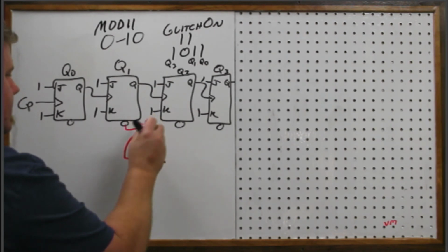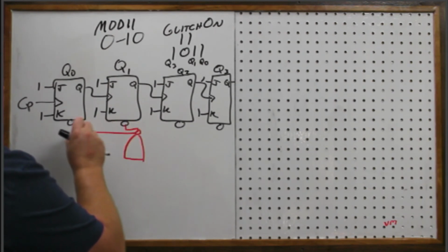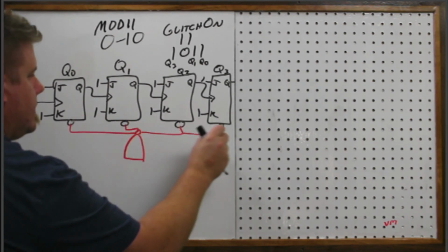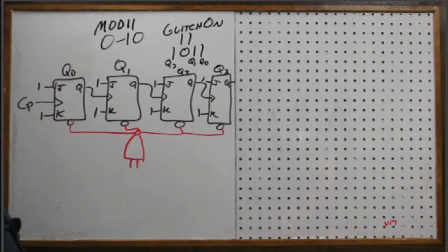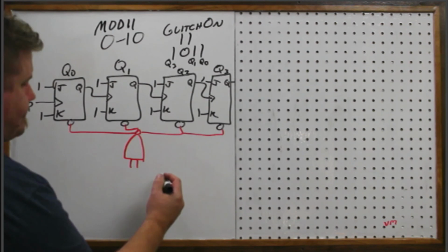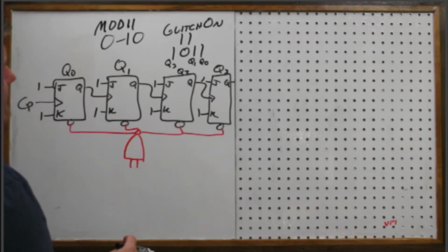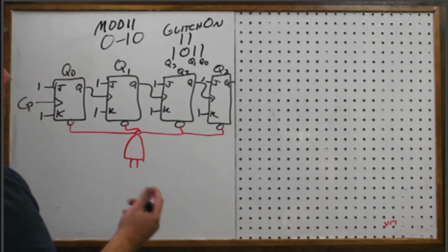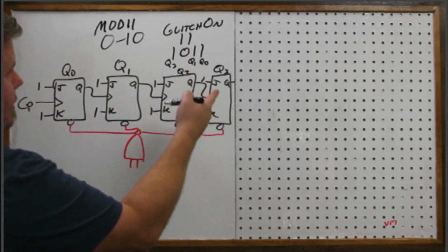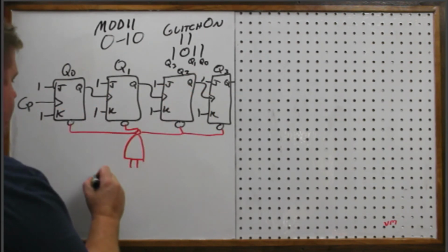Okay. So let's say we have no choice. We have to use this last NAND. All right, so it's no different than what I asked you about earlier, where, you know, how would you make a 3-input gate out of using just 2 input gates? Same thing applies here. I can take my Q, let's take Q0 and Q1 and AND those together.